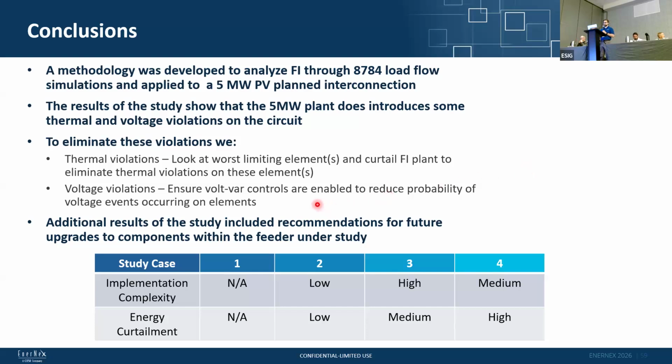And then to eliminate a lot of the voltage violations, I don't think I mentioned it earlier, but those volt var controls really help to reduce the probability of voltage events occurring on elements. So those were really impactful to look at in the study, and that's why we presented the results of the conservative volt var case, because it gave the best results to limit those voltage violations.